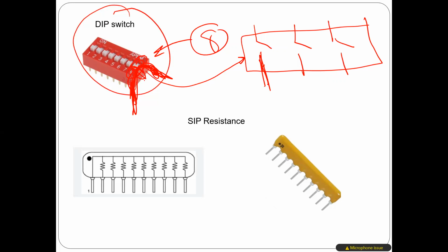So we have 8 switches. For sure, you may not need all of them. Whatever you need or don't need, they are separate. So you can use 1, you can use 2, whatever you use. You don't need to use the 8. But you should understand, every one here is actually a separate switch, and each switch has 2 terminals. Look here, we have a pin here and a pin on the other side, for each one of them. At one position, you can make it an open circuit. At the second position, you can make it a short circuit.